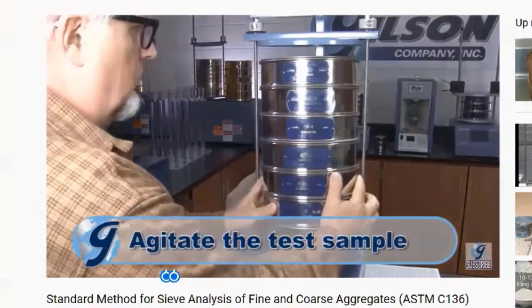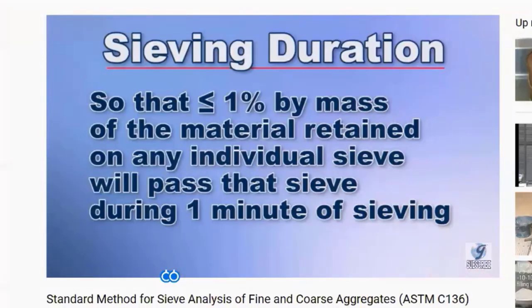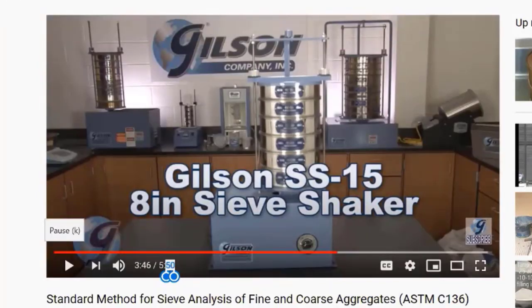Agitate the sieves by means of a mechanical sieving apparatus for a sufficient period of time so that not more than 1% by mass of the material retained on any individual sieve will pass that sieve during 1 minute of continuous sieving. I can allow this to continue, but hopefully that gives you a sense.